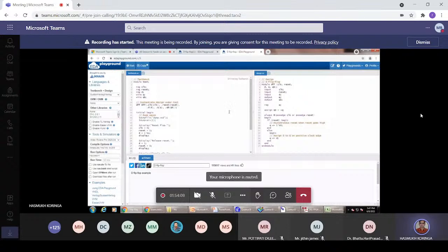So here we have to instantiate the design, using port name mapping. The clock is a port of the design file, and the clock inside the bracket will connect with the clock of the top module, which is the test bench. Once we instantiate the DUT, the next task, if needed, is to generate a clock. For that we write one initial procedure to generate the clock.